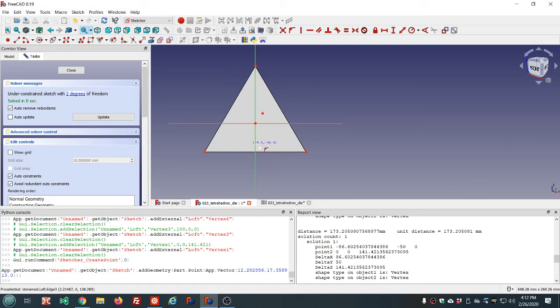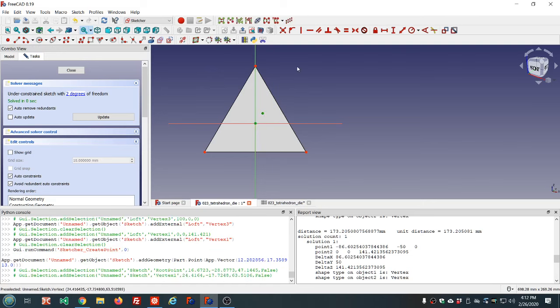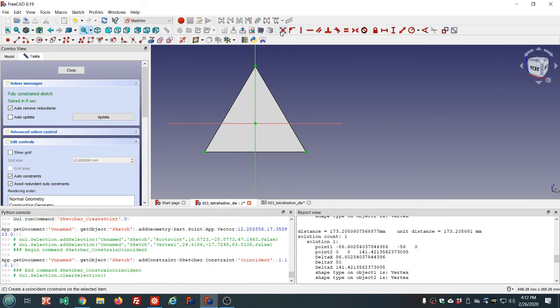So we can add our point, select the center in here, and apply the coincident constraint. So we're really done with sketch number 1 at this point. But I want to indicate to myself that I've already used this side, so I don't get confused. We're not going to be doing anything with this sketch except using that point as a reference for a draft array, like we did with the die in the other video.